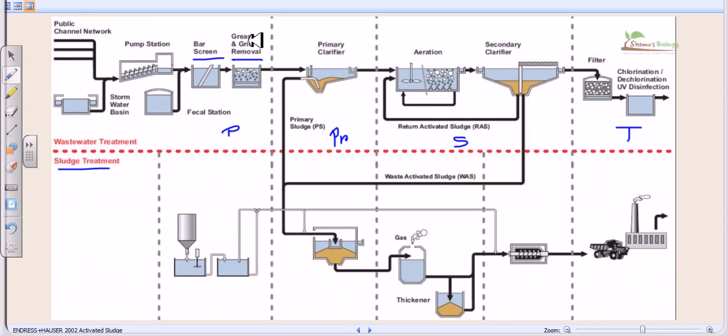For example, fat materials like grease materials are not water soluble, and they will be floating on the water if we give time for settling the other things down. Now in this case we utilize a fat trap, and we can see all the grease which has passed through the bar screens can be coagulated in this tank, and we can have grease balls formation which will float. We take those grease balls and scrape them off with the help of the scum removal, and leave them aside, and it removes all those grease materials.